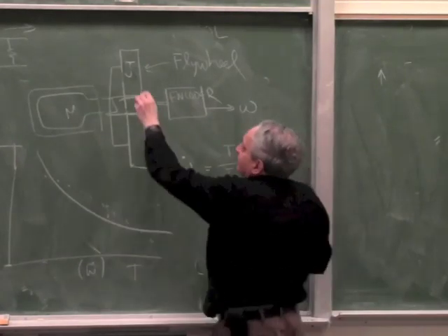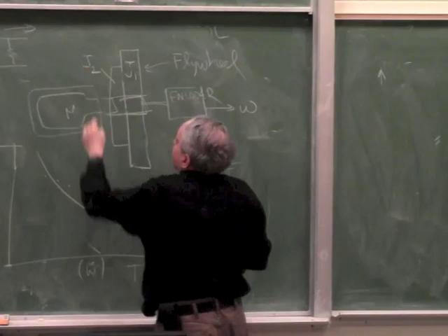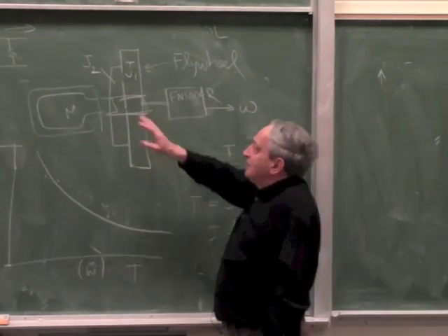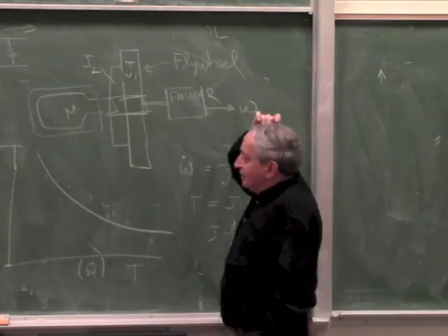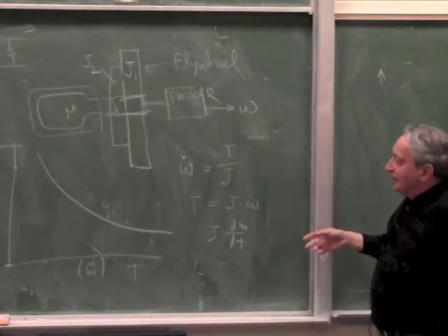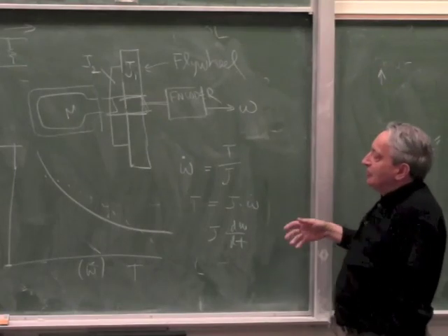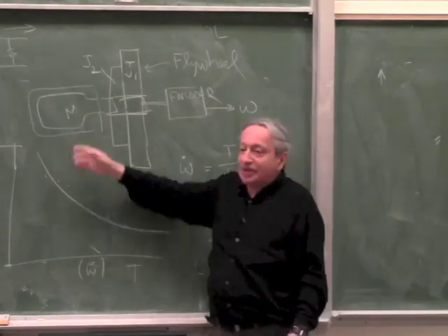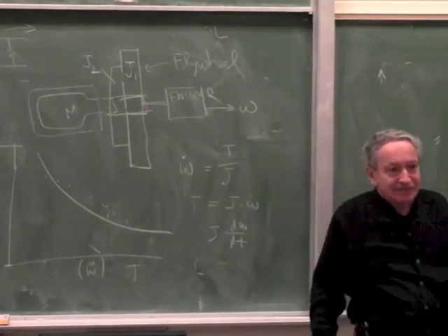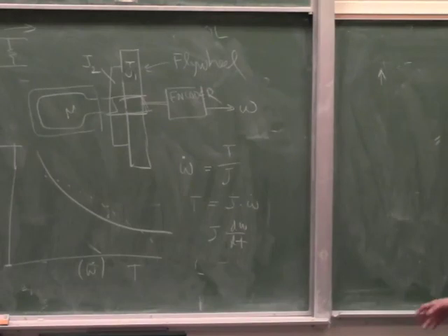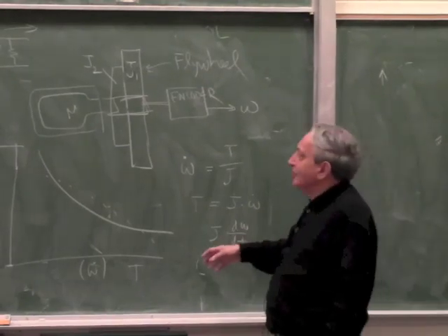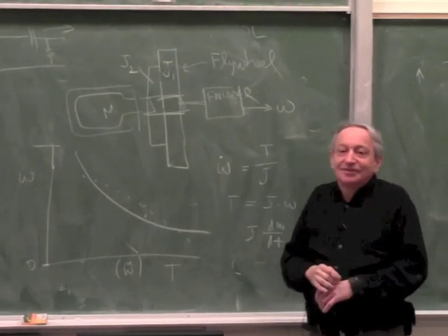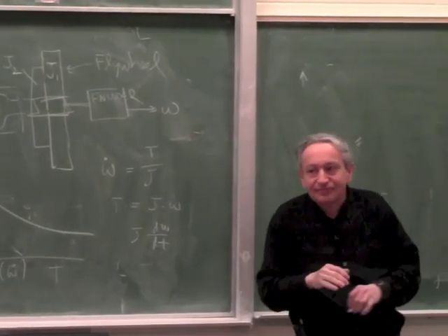So it's the same as adding another one. Okay. So you say this is J1, you add J2, and J2 could be the motor inertia. Okay. Now, in this case J2 is not known. However, if you do that, you'll get another plot, and between the two plots you can calculate what the internal J is. Okay? So basically the most elegant way to plot torque versus omega is just let the motor start and just monitor the speed. Okay? Good.